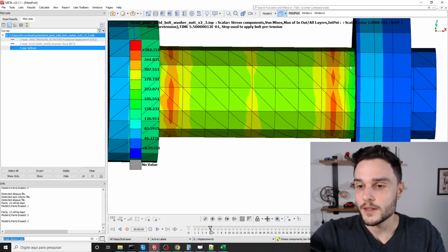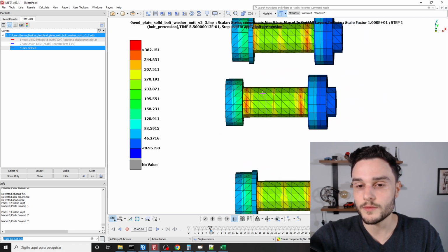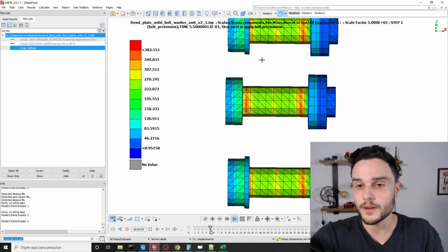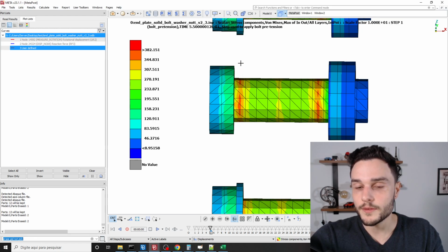this layer of elements. So what we can do here is I'm going to use the not function. I'm going to select entity selection mode, create a box selection. You see that I have this view that has nothing behind. I'm going to get a view like this, use the left mouse button to create a box selection, selecting these elements here.